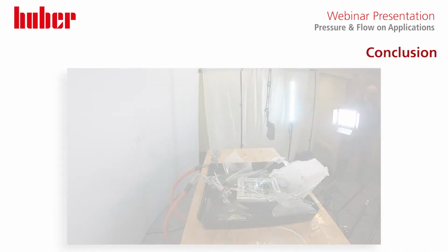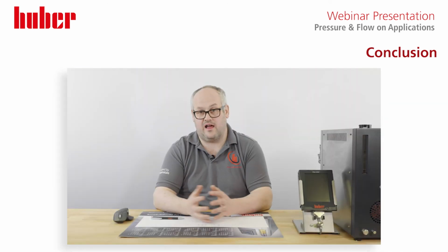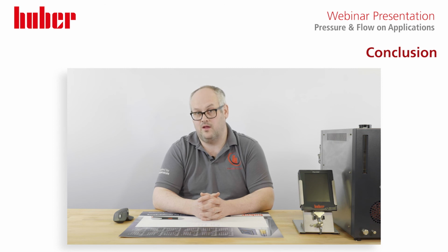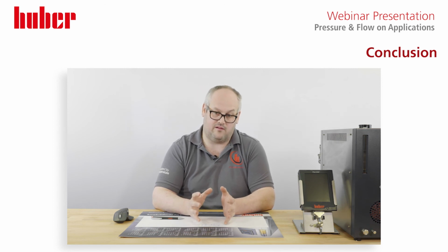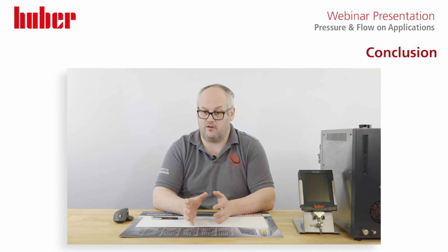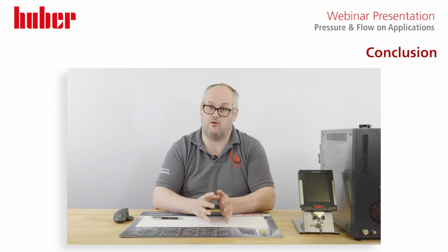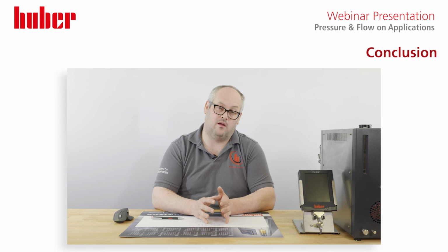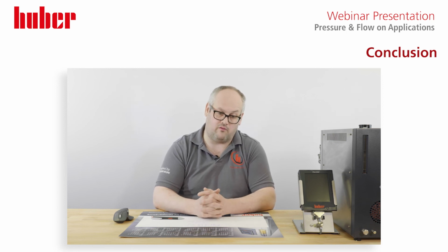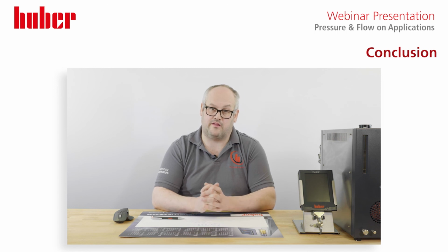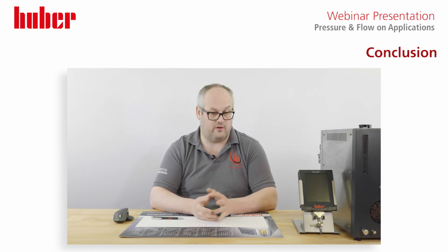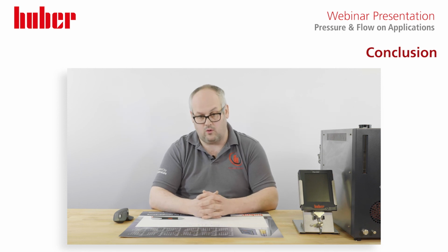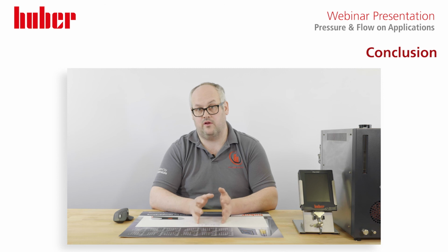See? So as you can see, the glass doesn't survive hydraulic pressure being applied. The reason I've done this is just to prove that it's not a TCU that can apply it. If you've got the correct TCU that's either open bath or has a built-in passive expansion tank that will accept your increase and decrease of thermal fluid volumes, it's key to remember that. If you're really still concerned, fit pressure relief devices to your lines. We'll happily advise. If you want to do quick disconnects or shut-off valves, we always recommend pressure relief devices.